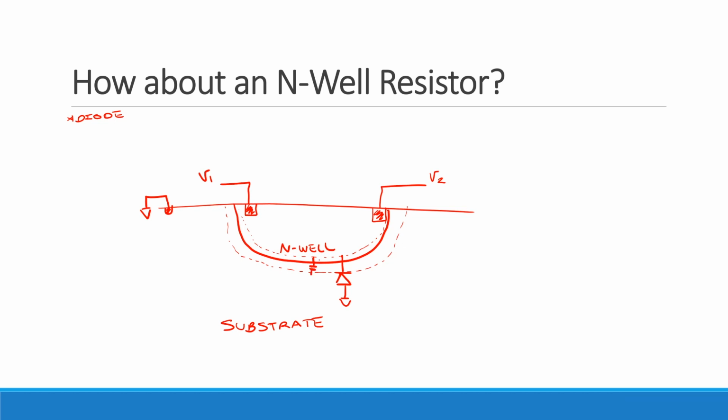Now, why is capacitance kind of bad in this context? Why do I not want capacitance? Let's maybe ask it a different way. If I built a resistance, what kind of impedance was I trying to get, high or low? I want a high impedance, right? Well, if I have a capacitor, then at high frequencies, I'm not going to have high impedance anymore, right? So that's why, fundamentally, if I have a resistor and I get a capacitor, that's kind of bad news, right? Okay, that's all goodness.